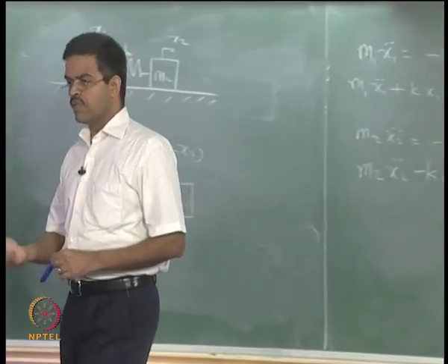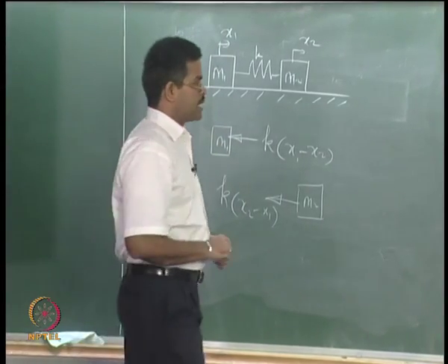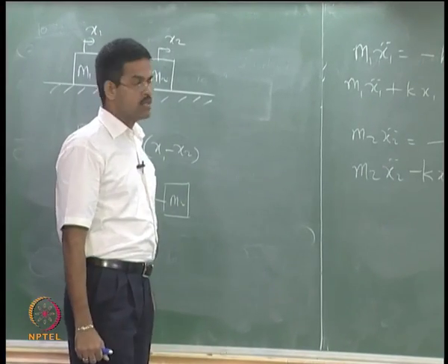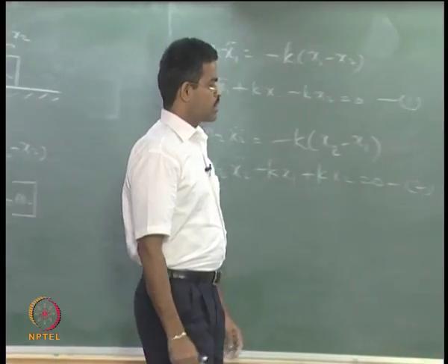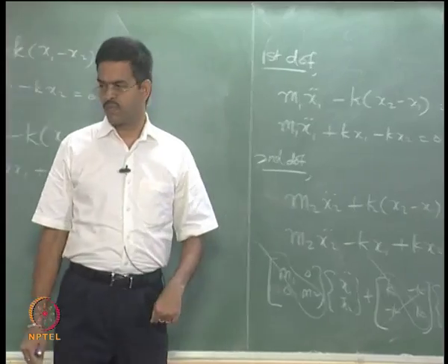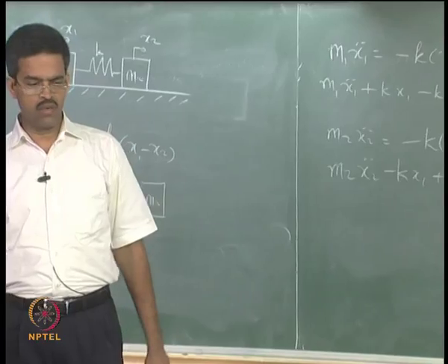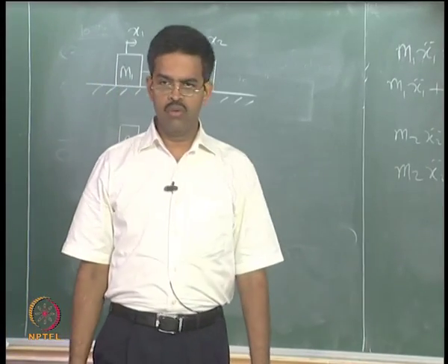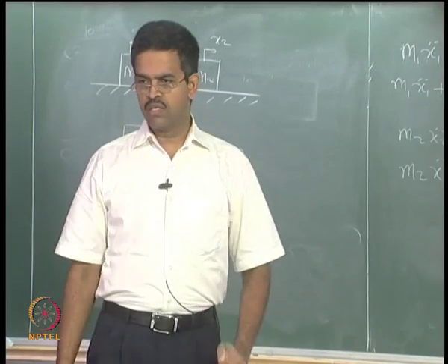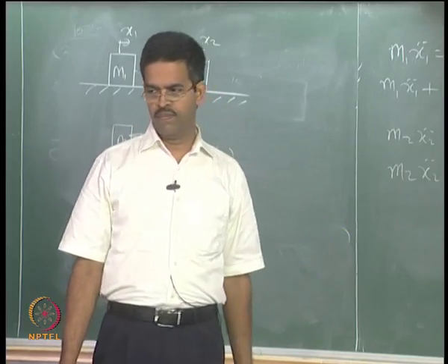So you can adopt any method for writing equations of motion. We have demonstrated it using Lagrange's equation, which is the energy principle, as well as Newton's method, which you already know. Generally, equations of motion are comfortably written using Newton's method because they deal with forces, whereas Lagrange deals with energy principles. When you want to minimize or optimize or talk about response control in terms of energy mechanisms, then one can write equations of motion using energy methods. Otherwise Newton's law, which adopts the force technique, will be simpler.